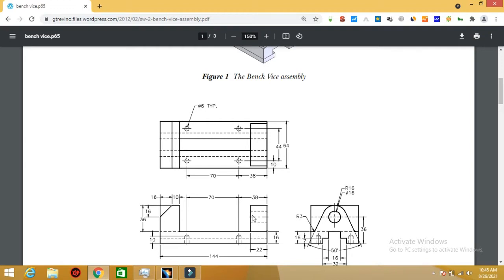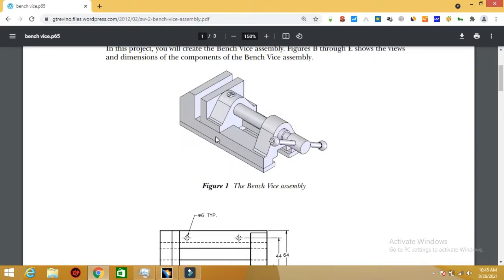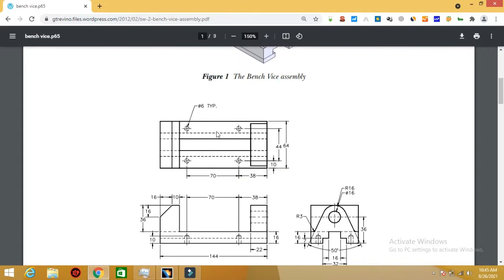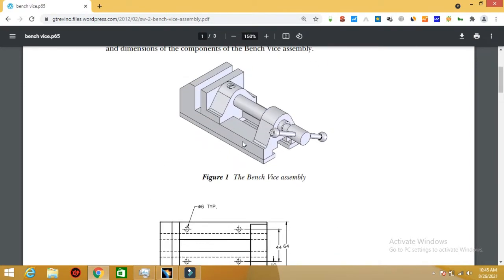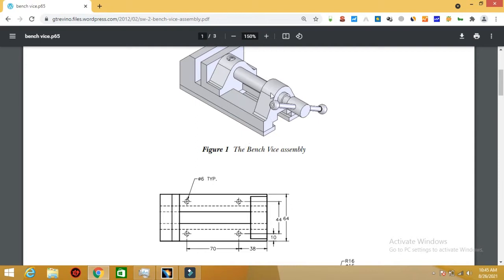Okay. So looking at this 3D figure and getting these views, I would like to start from the front view. So the front view shape is like this. Because this is a curved part, I will make this separately. How do I know this is a curved part? If the 3D view is not given, here it is given, so it is easy. For your understanding, I have kept the 3D part also.